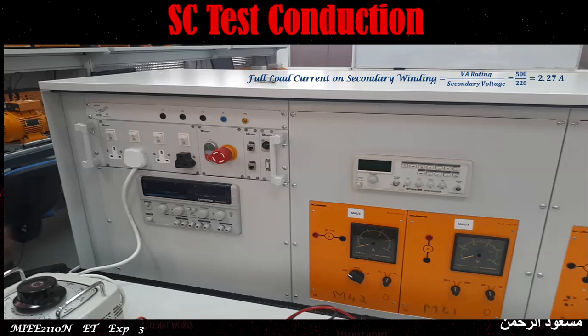Now we have short circuited the secondary side, so the rated full load current on the secondary winding is equal to the VA rating divided by the secondary voltage. The transformer we are using is of 500 VA rating, and the secondary voltage is rated 220. If you divide, you will get 2.27. Now note this current. We have to switch on the supply and vary the auto transformer such that this calculated rated full load current is circulated in the secondary side, the short circuited side.